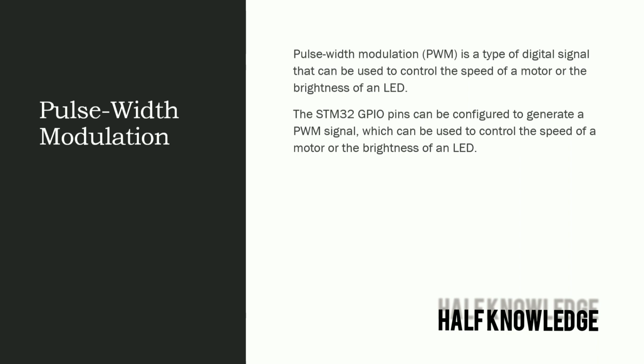Move on to pulse width modulation. Already we know that pulse width modulation is used to control the intensity of LED as well as motor speed. And one more thing, this is important in PWM. I think you catch up, that is, duty cycle plays an important role in PWM. If you change the duty cycle, we can control the motor speed and the intensity of light and LED. Practically I'll show later. Just keep it in your mind.